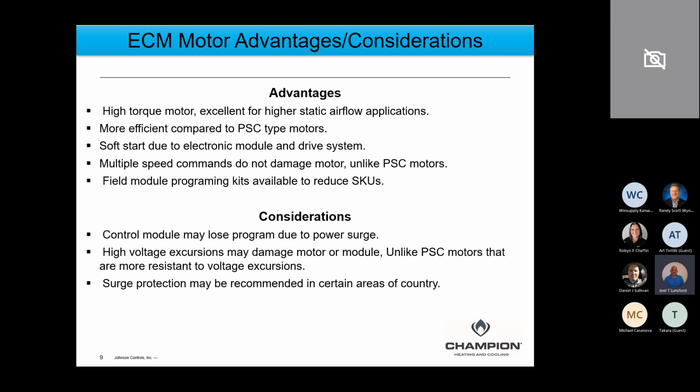ECM type of motors, variable speed types of motors, they will ramp up and overcome, or certainly do a better job of overcoming, that static pressure in that older duct system. So even though it's not a cure-all, to your good point, it's a definite improvement over a PSC blower when it comes to marginal duct systems.